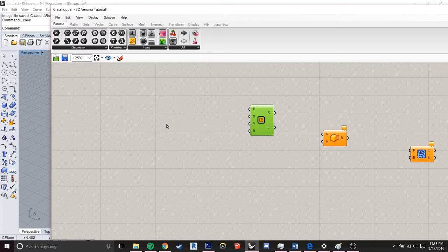Now let's grab ourselves some number sliders. A real handy, quick way to do this is to just type it in here, and then with the amount of decimal places you want, you can type however many you could ever need. I'm just going to stick with one decimal place here. I'm going to type 20 is less than 0, which will automatically put it at the top of 20 there, and have 0 as the bottom part of the range. We're going to put one for Y here. I'm going to click on it and hold Alt to make a copy, and put this in for X.